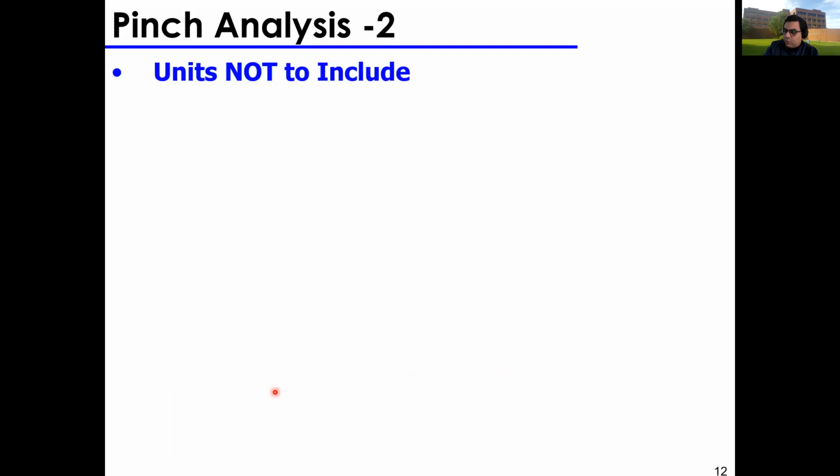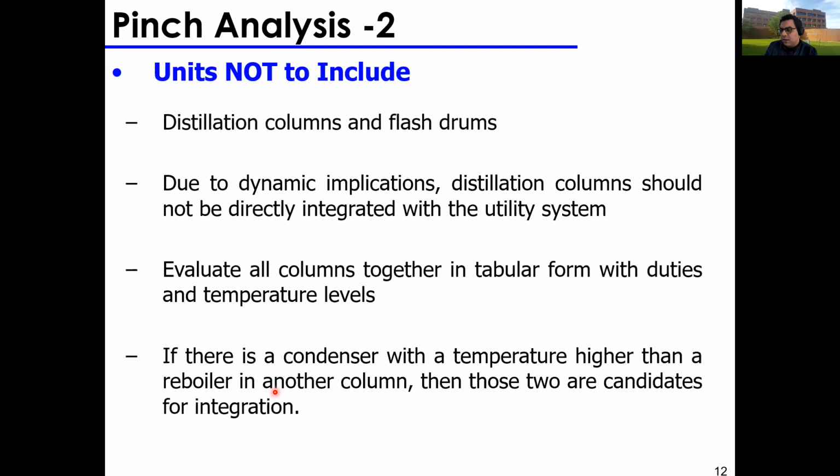Second thing is, when doing your preliminary pinch analysis, you should never account for your distillation column and flash drums. Again, these are processes very sensitive to temperature, so we don't want to make any promises on them at this very early stage, okay? So please try to understand what's going on here. Try to implement some of these ideas in your design project, and it's a baby design project still. Try to implement some of these ideas into it and try to get into the mind frame of thinking in this way.